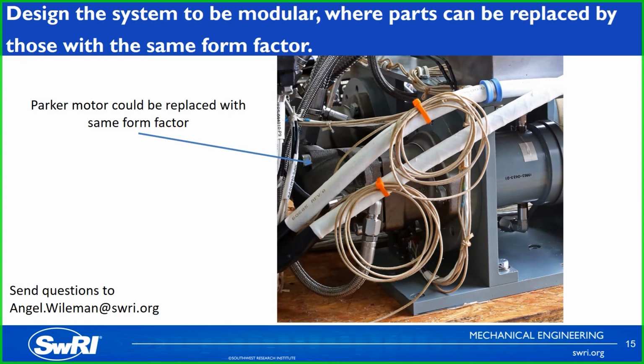We knew it was kind of risky to try and run at the 9,000 RPM. And so we ensured that the other displacement motor we selected also had the same form factor, just a little bit of length added to it. So there was no additional machining, there was no additional reassembly. We were able to just take the motor right out and replace it directly with the higher displacement motor, and that way we were able to eliminate some of the downtime that we had as we were trying to make sure that we could meet the requirement in the commissioning process.